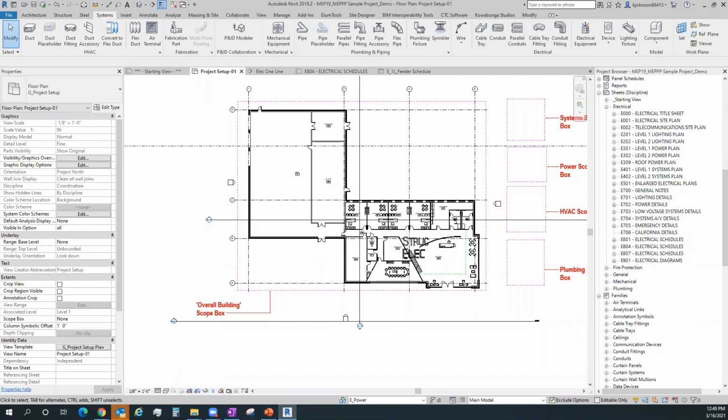And in those cases, those programs are letting you build entire electrical equipment systems and even power systems, and then make OneLine diagrams in those programs, which gives you the ability to have DXF files. And the DXF file could be linked as just a normal CAD link at that point. So as you continue to make changes in, say, SKM, you could always export those out to DXF, hit the reload button in your Manage Links tab, and have the updates come from those programs easily.